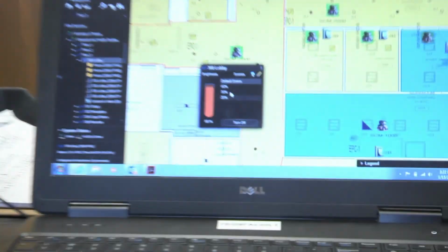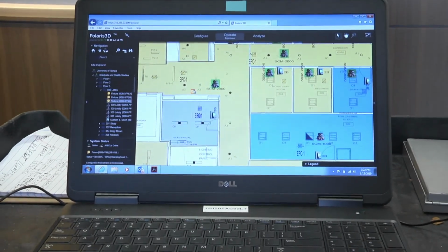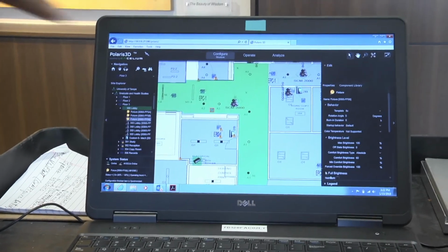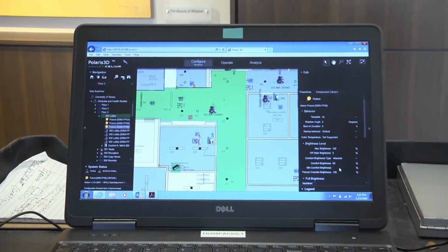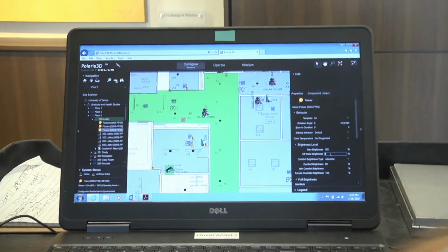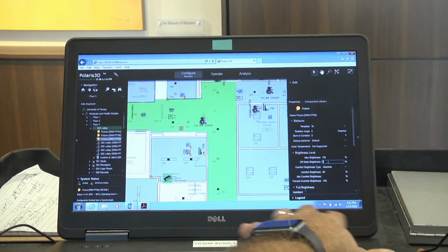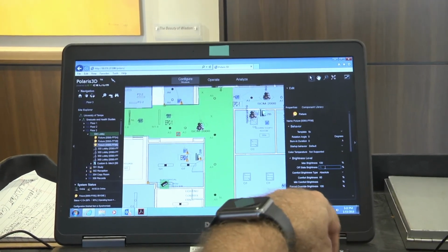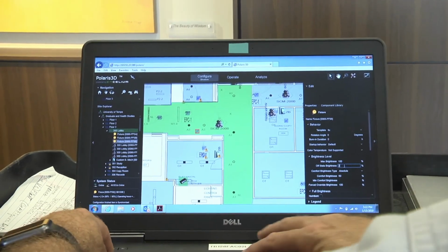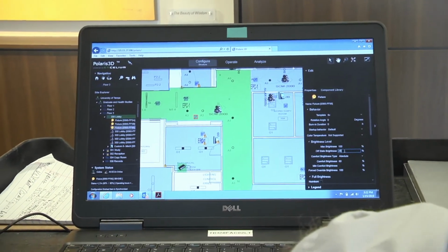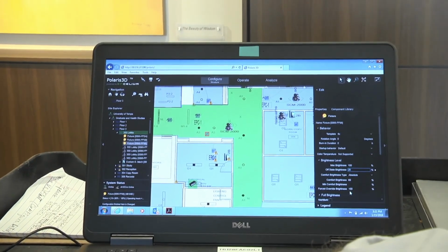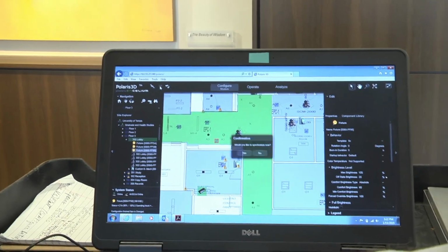Select the module we just added a while ago. This one, yep. Go into configure, structure, and in the properties section over here, there's a turn off delay. Look where you see turn off state brightness, I'm sorry. Put that to 20. It means that 20% is the off state. So it won't go off completely. It will go to 20% in its off state, right? Again, you put something else. You know what you have to do? Yeah. Convert forced override brightness. Yep. So. Save.